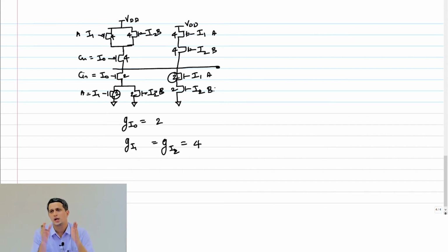So think about it. When, let's say that this full adder is being used in stage K of the ripple adder, A and B have already come in at time 0 and would have discharged this intermediate node, either this or this node. Now the carry in, it's just waiting for the carry in to come and finish its work. Right? Of course, if the carry had been generated, then what would have happened?